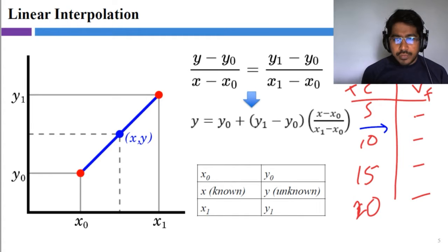So in such a situation, what we are going to do is interpolate between the two data points we have, and we assume in this bracket or interval, the properties vary linearly with temperature or pressure, right? For an example, if you look at this graph here, you can see that you have 2 points.